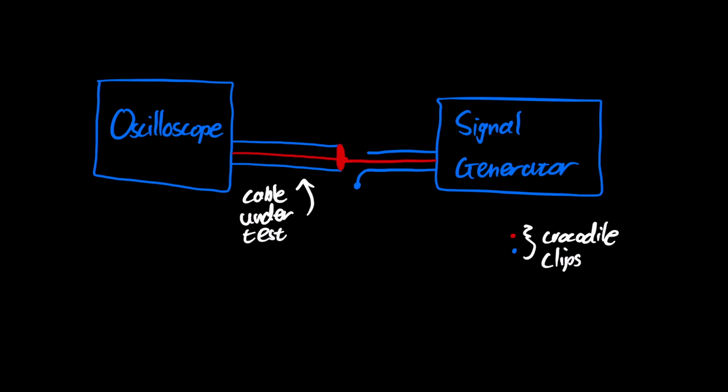Now, you may be wondering how a common mode current may flow, especially since the negative crocodile clip is left disconnected. To have the full picture, the protective earth connection and the power cables leading to both the signal generator and the oscilloscope need to be considered.